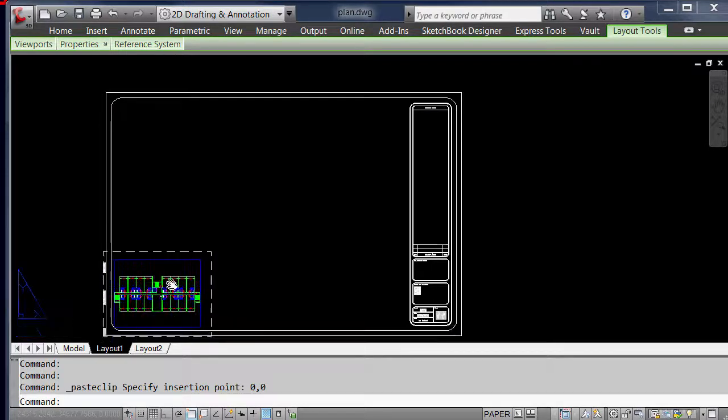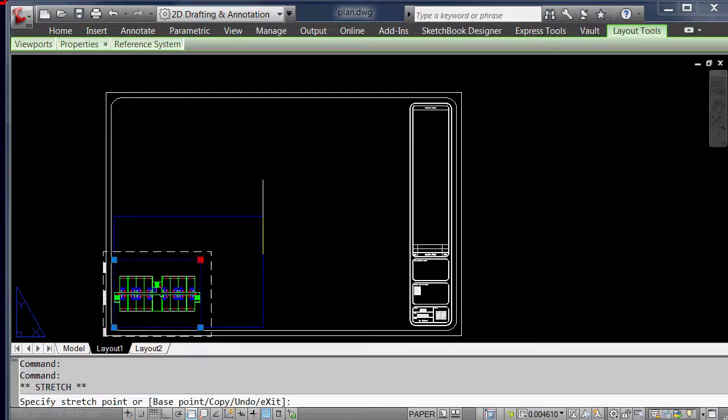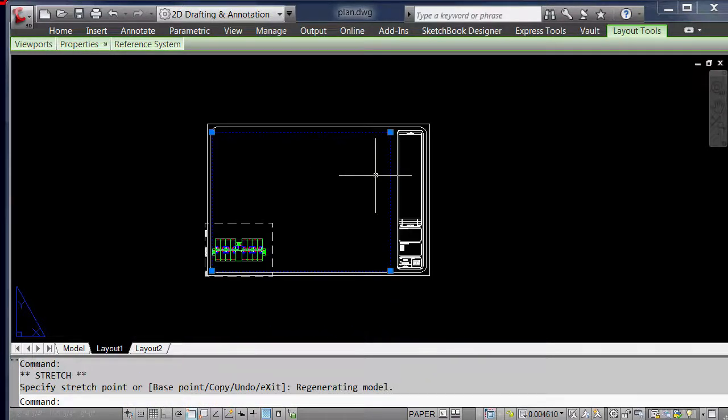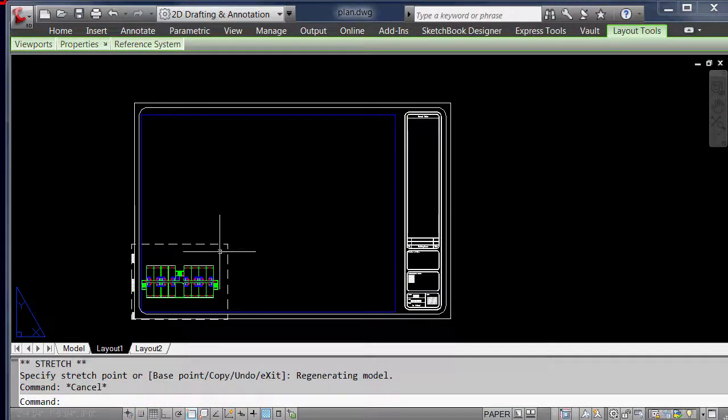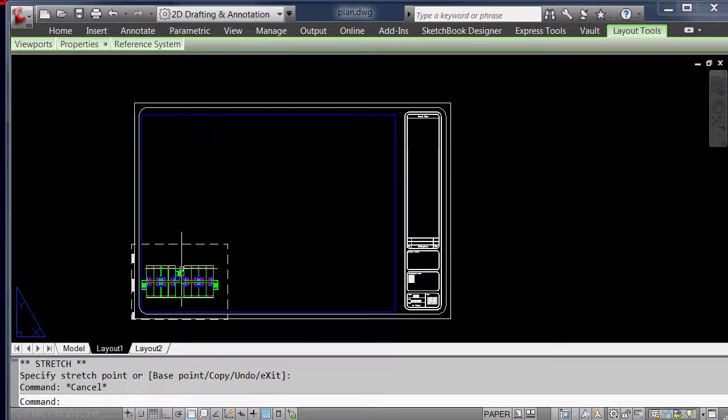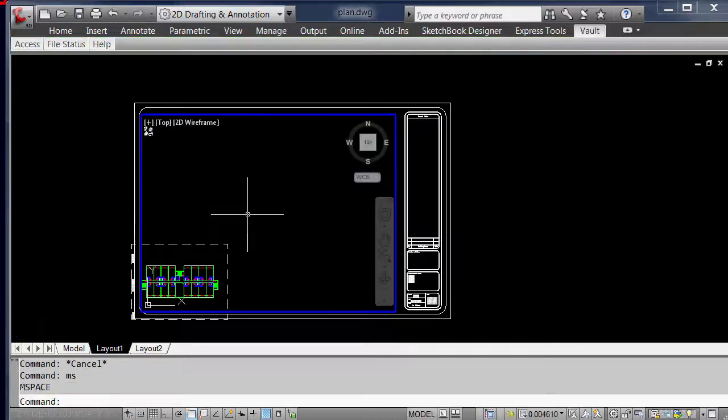Okay, so there we go. And if I remember right, this is a 24 by 36 inch drawing. All right. Okay, so now I've expanded my M view, which is up here. And now I have my picture sitting right here on the lower left. Now I need to center that up. So type model space so that I can open up a window here. We're going to get into model space, paper space in a little bit. Okay, we're going to go ahead and center it up.